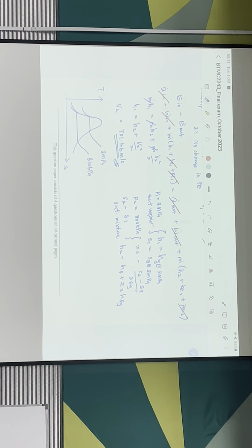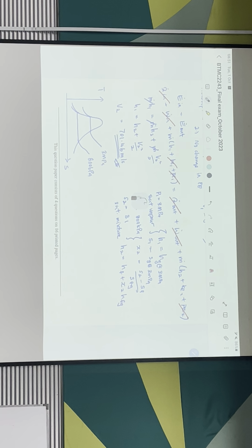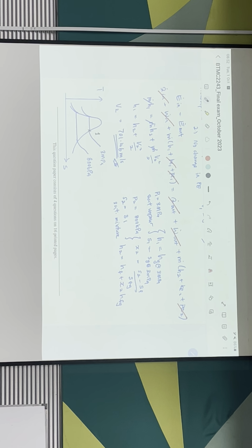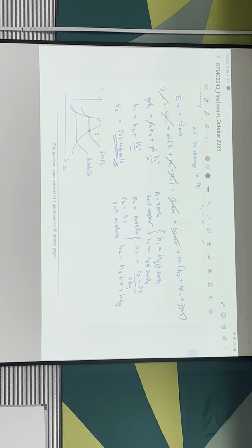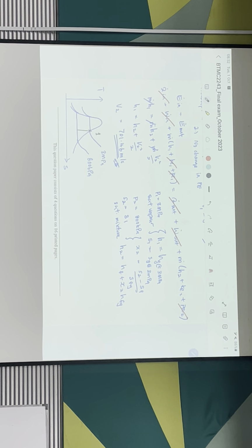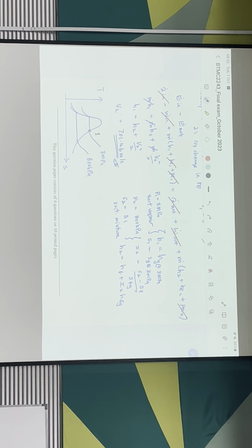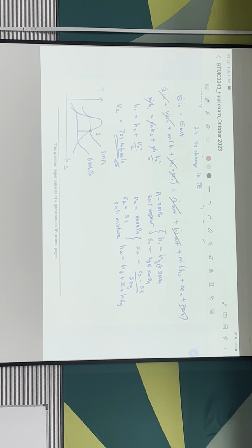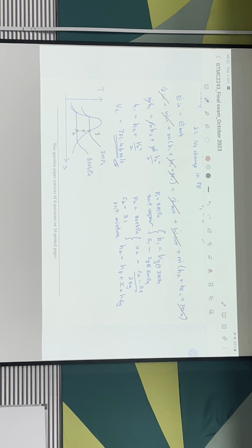This one is very straightforward actually. You start off with a saturated vapor, so state 1 is here. Since this is an isentropic process, like we mentioned, at least we are assuming maximum velocity, so isentropic process. So it should go all the way straight down, and then state 2 is here.